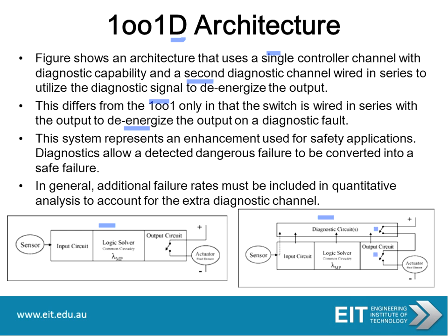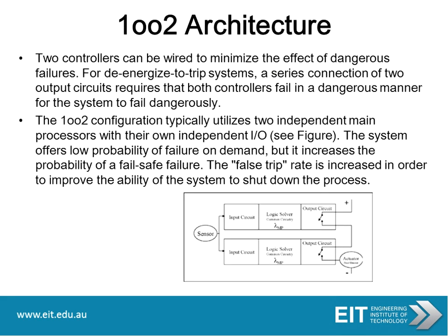So you can see there it's wired in series. So it's an enhancement that's used for safety applications, and the diagnostics allow a detected dangerous failure to be converted into a safe failure. So now it can fail at the end of the day, short circuit. So we've got something in parallel that we can use to change that to a safe failure, which was previously a dangerous failure. So additional failure rates must be included in your quantitative analysis to account for that extra diagnostic channel which is now being added.